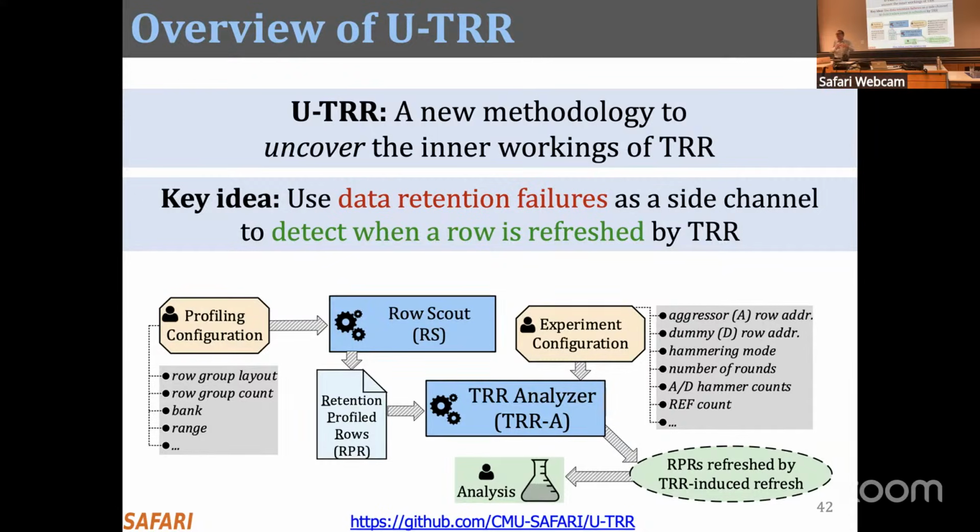We tried understanding retention times a lot for more than a decade. And we tried understanding RowHammer a lot for more than a decade also. This kind of puts together these two in an interesting way, connects them in an interesting way. By using the understanding that you've developed for both, especially retention failures, you can figure out what's going on internally inside the DRAM chip.